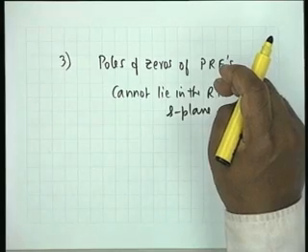What is the reason? It has something to do with the real part. It is a passive network. You see, all positive real functions, this is interchangeable, impedance, admittance or positive real functions. All driving point impedances are PRF. It can be shown that all PRFs can be realized by driving point impedance of passive networks.